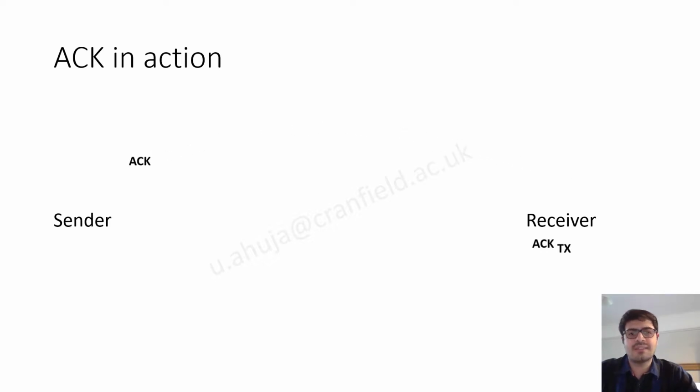The receiver now sends the ACK back. The first packet is sent to the receiver, and then the ACK is sent back, and then the second packet is sent to the receiver. Along with that, ACK is sent back, and then TX is sent, and after that the acknowledgement is received again. The cycle repeats. In this way, with the TX and acknowledgement sent at the same time, we can not only limit the extra usage of the acknowledgement packet, but also signal at what times acknowledgement has been sent along with the TX command received.